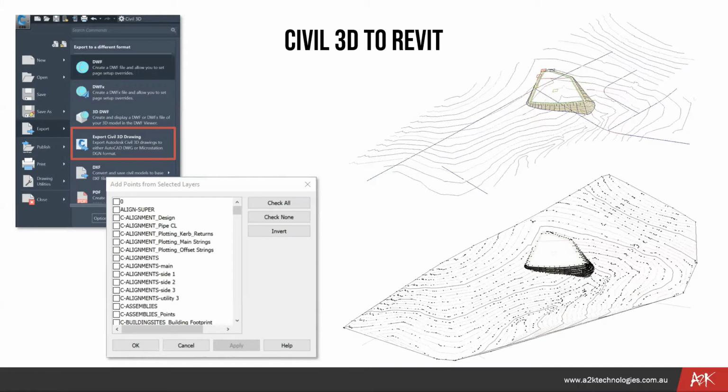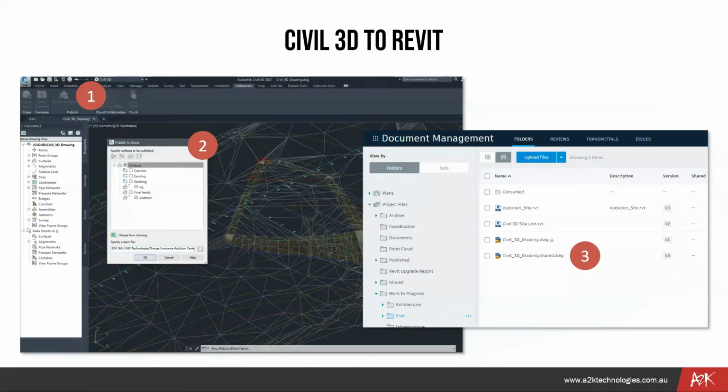Understanding which layers, lines, and points that Revit is going to generate means that it might be difficult to separate certain site features, such as its platform versus the existing conditions. So in this case here, I might just want the existing conditions, and I might want the pad or the platform here as a separate Revit topography, but in this case, they are all considered one object and very hard to separate. So what Civil 3D does, with the use of BIM 360, it helps us to process the Civil 3D information in a more simplified and usable method for Revit.